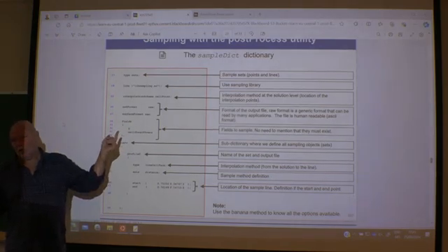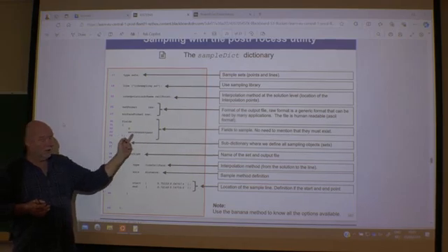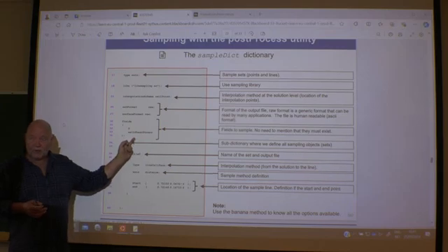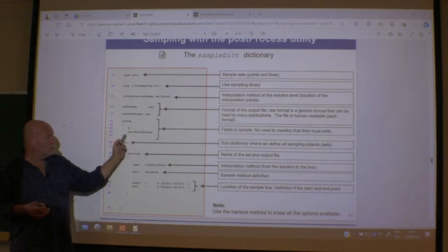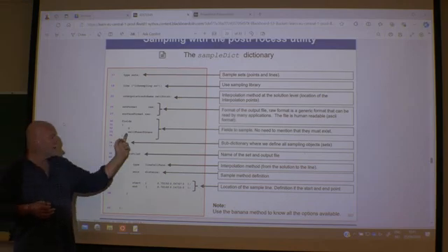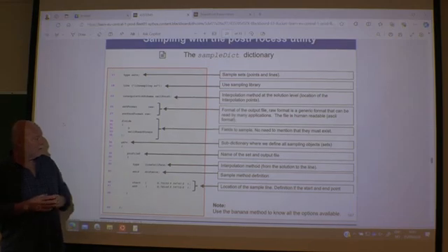Well, that one we always have. But what about this field, wall shear stress? That's not normally computed. Meaning, if you want to extract data from such a field, you have to create it first. So then you need this function, or you could also use postprocess to create this field first, and then you can afterwards extract the data from it.